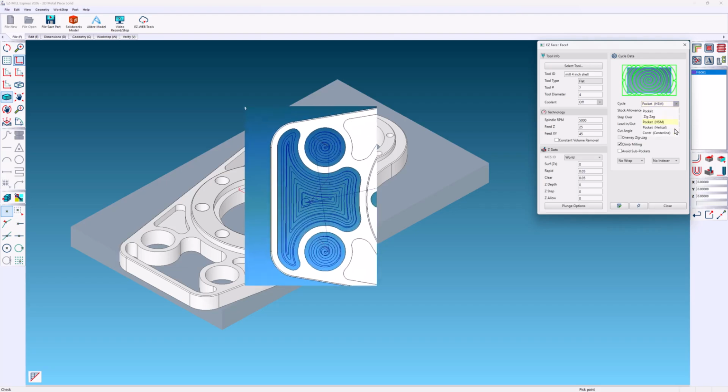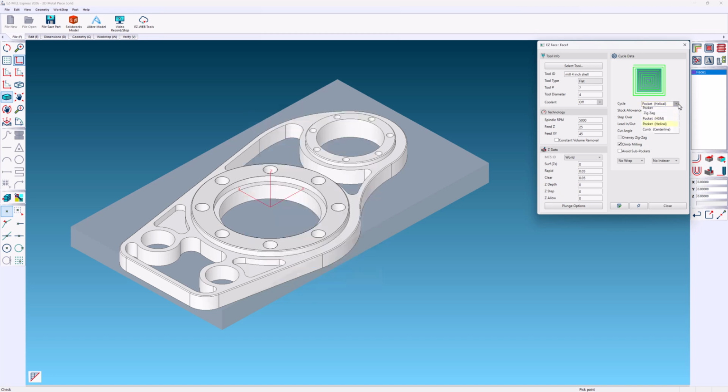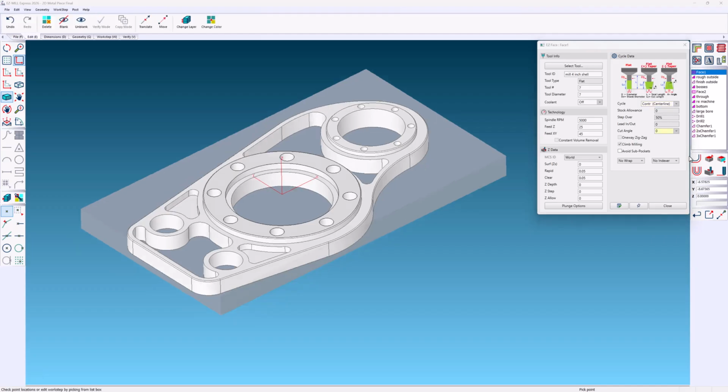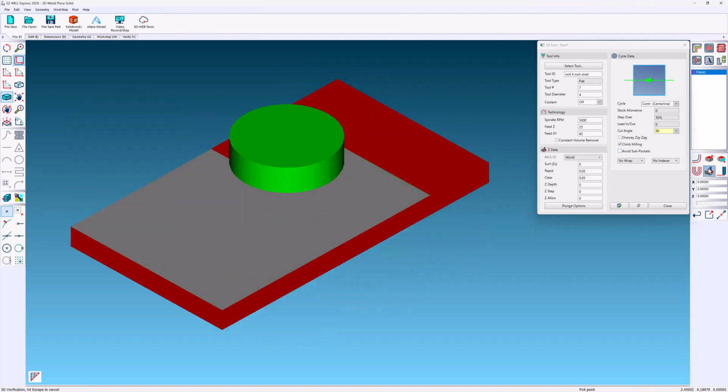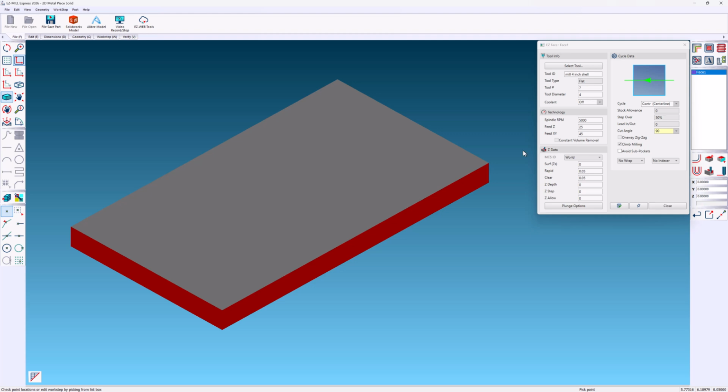Helical can be looked at like the yellow brick road. It's a continuous spiral until it reaches the end where the entire perimeter is cut. Centerline positions the cutter on center of the selected surfaces along the length or width. If the cutter is large enough, EasyCam generates a single pass. If the cutter is not large enough, EasyCam adds the necessary passes to complete the job. With our new version, you can verify to calculate and visualize the toolpath while the operation is open.